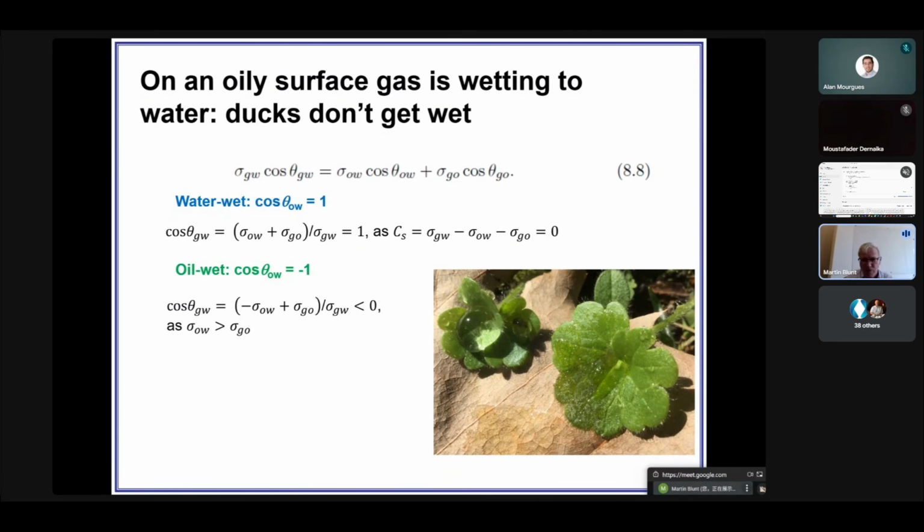So we've got oil, water, and gas all present. Now, what most people think is, well, that's easy. Let's take the water wet paradigm. So imagine we did have a rock that was water wet. What that means is it's wetting to water in the presence of oil. Now, when I inject gas, it is true, oil spreads on water. Gas is the non-wetting phase in the presence of oil. So gas is non-wetting to oil, that is correct. But it's also, of course, if it's water wet, non-wetting to water. So you have a water wet system, you say, well, this is obvious, water likes the surface. If I have oil or gas in the pore space, oil will be non-wetting or gas will be even more non-wetting. Okay, so that's the obvious case. That's the water wet case I've shown there.